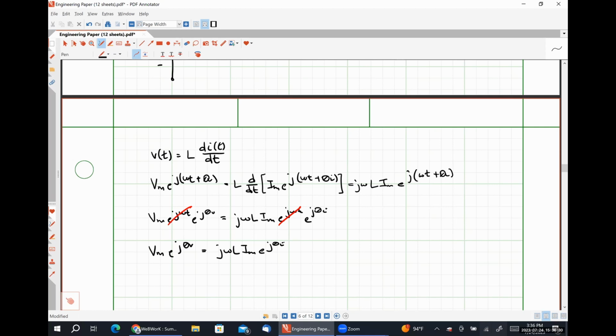So I'm going to show you guys something over here on the right-hand side of the screen. So this is my complex plane. Here are my real numbers. Here are my imaginary numbers. So if I go out 1 unit in the positive real direction, or the number that we would commonly call 1, that is the same as a polar form complex number 1 angle 0, a rectangular form complex number 1 plus j0, and an exponential form complex number 1 times e to the j 0 degrees.